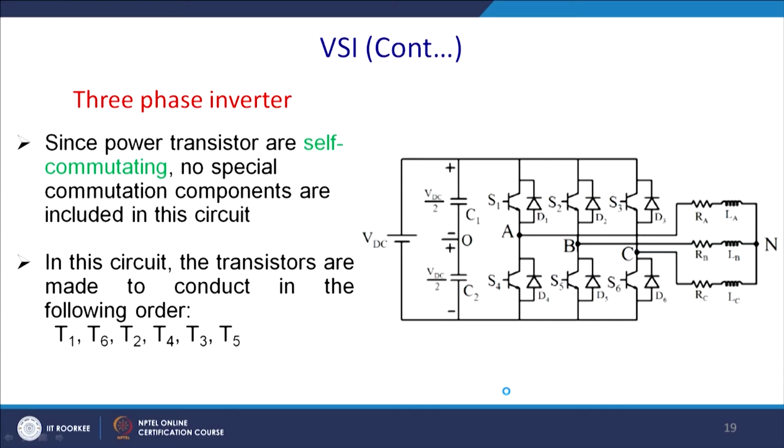So you will be using GTO, IGBT or power MOSFETs, and if you would like to use thyristors, then you require to incorporate an auxiliary circuit for the commutation. There are different kinds of auxiliary circuits, named after the inverter, like the McMurray-Bedford inverter. We used to study it in our BTech days, but now it is gradually phasing out with the advent of modern switching devices.